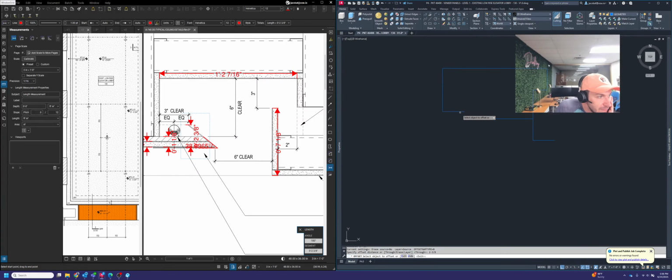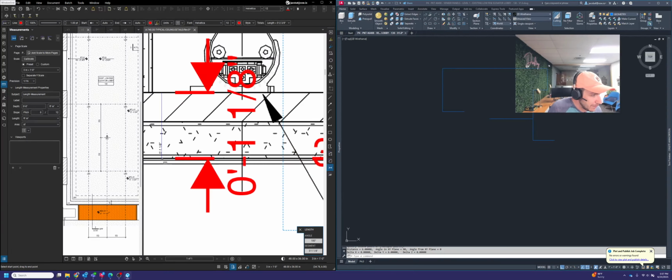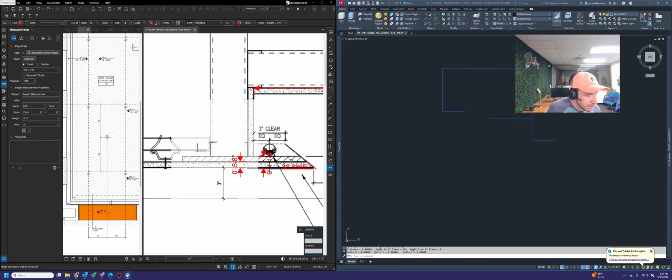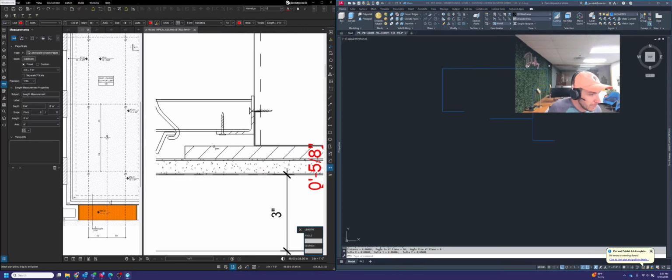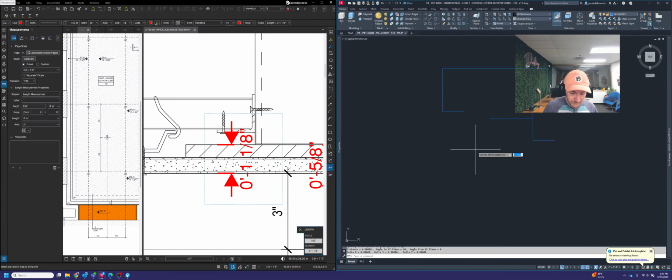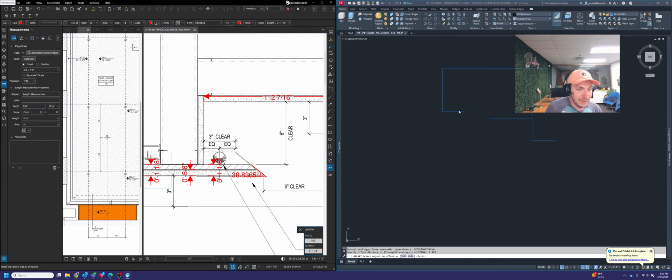That's going to be in, let's see. Oh, you know what? Hold on. I think I did this weird. So 6 inches down to there would be to there. Okay. And so I guess if I was to find out from there to the bottom of the drywall, I think that was the 1 3. Sorry, I got a lot of dimensions happening now. Gotta clean this up. Okay, so from the top of this plate to the bottom of the drywall is 1 1/8. Okay, so that makes sense. So 1.125 or 1 1/8. I need to come down that 1 1/8 here.